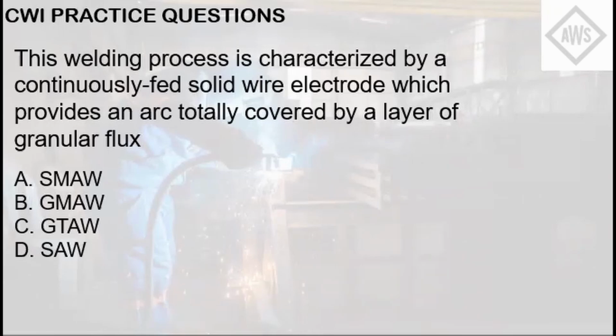It's called submerged because the arc is submerged in a layer of granular flux, and it is a continuously fed solid wire electrode through that machine.